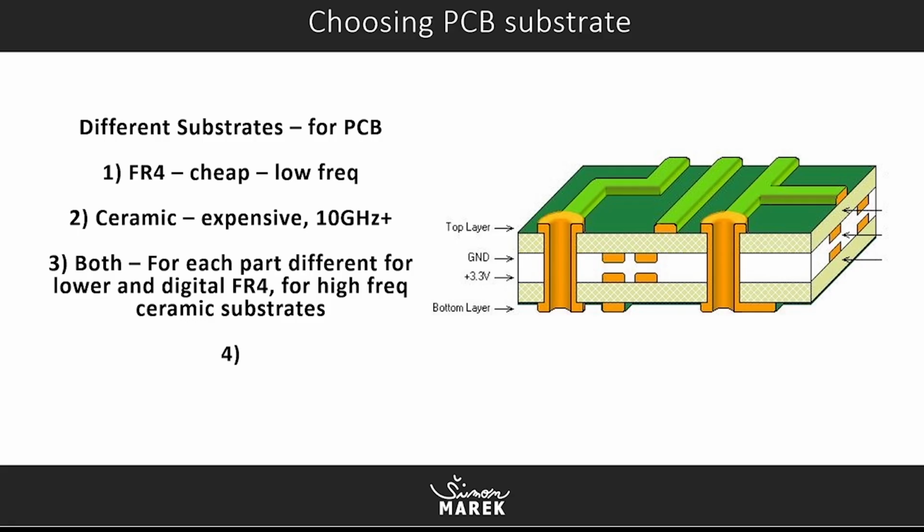There are ceramic substrates which are expensive and can run reliably to 10 gigahertz, and they won't heat up and won't have any negative influence over your circuits. So ceramic substrates are highly recommended for very high-end circuits.